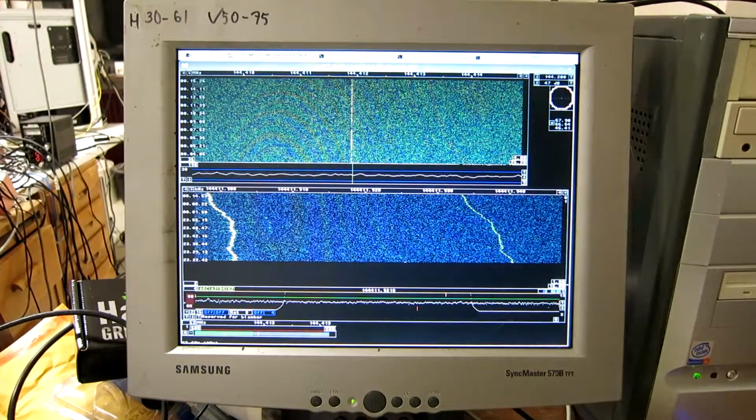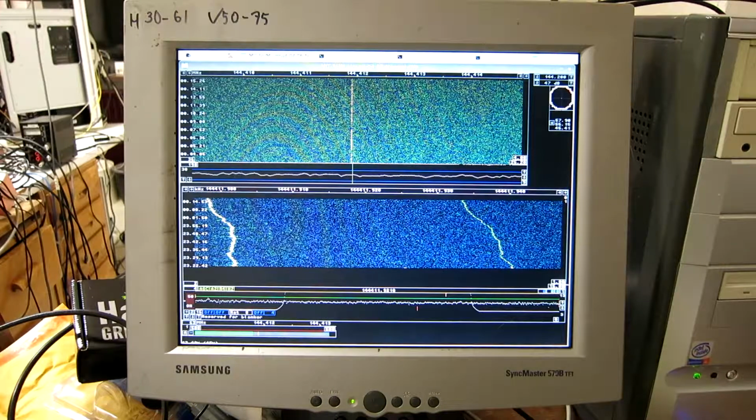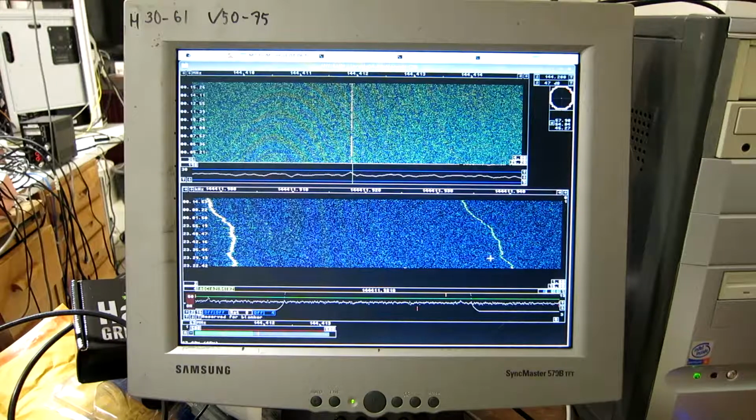Now some time elapsed with the 10 dB attenuation. It's quite clear that the frequency stability of my signal generator here and the beacon here is different. The dominating problem is the frequency drift of the dongle, but the frequency drift from here to here is twice as large as the drift from here to here. And I don't know really what the absolute frequencies are.